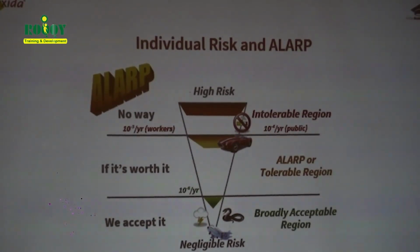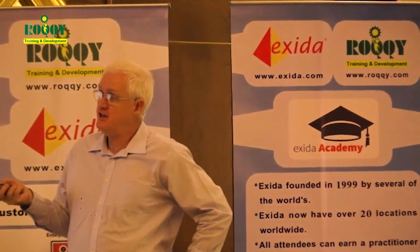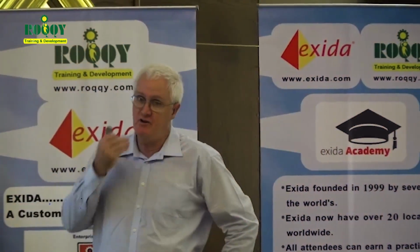If you've got 1,000 people on your plot, that means you're going to have one death a year if you're operating according to this. So at your boundary, in the ALARP region, you may be tolerating one death every year. If you start to do the calculation, if you've got 10,000 people, then you may have 10 deaths a year, which you may be regarding as acceptable. I don't know. That's why they've said it is the border. You've got to try and get to the green region, which is once every million years.